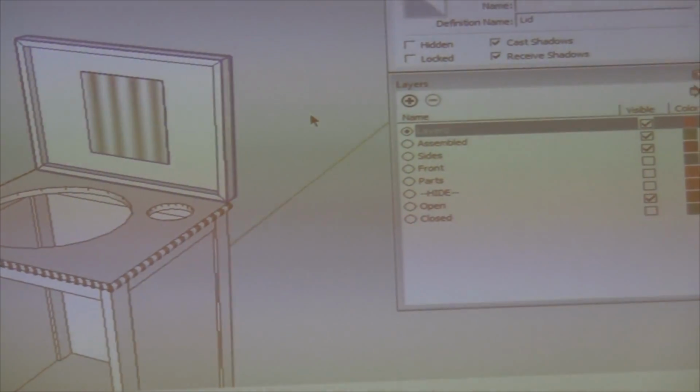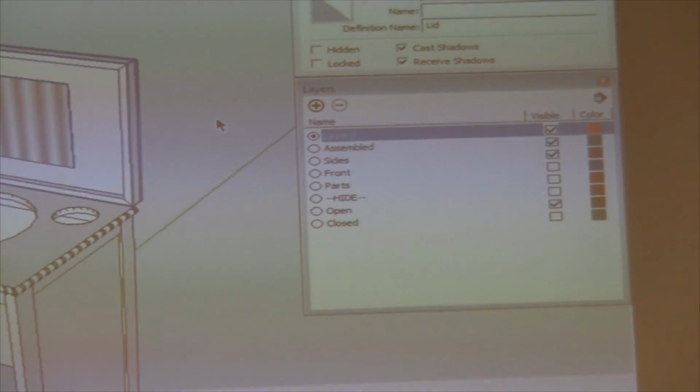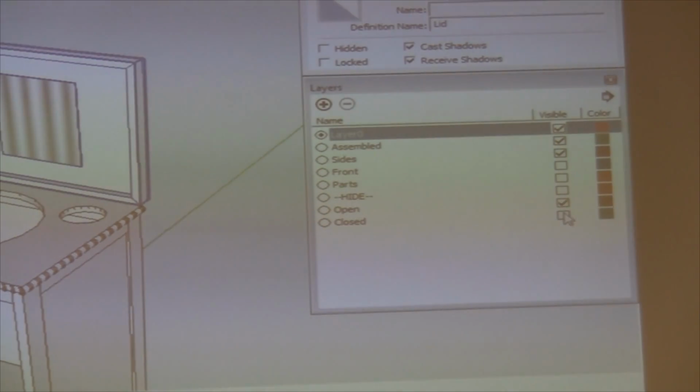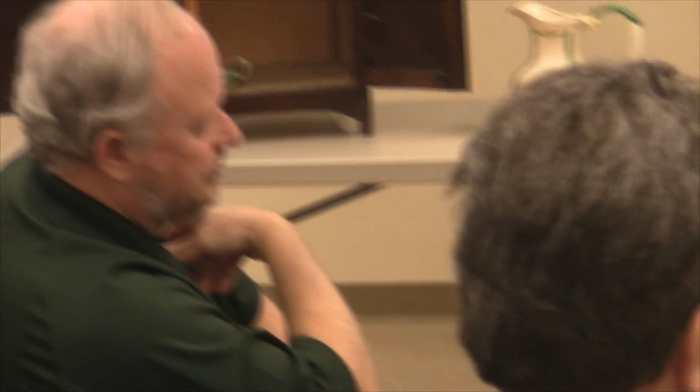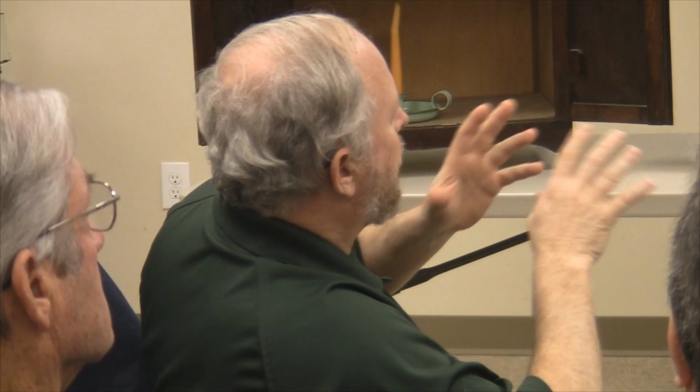The others are basically just the layers that you want visible. There are cases where you would draw on another layer, but it's generally not in our use for sure. Right. It's in design, where people use software for designing room space, like interior design or something like that. Yep. There's some needs for it, but for us, just don't ever draw on anything but layer 0.